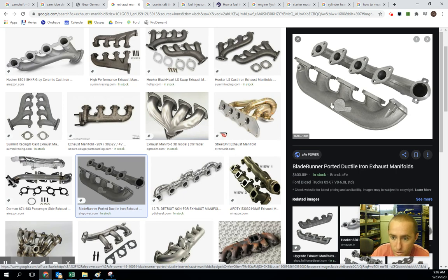So I have exhaust gases traveling this way and moving out towards the back of my car. That also creates a little bit of a vacuum in here, and it will pull the next exhaust and aid in this process so you don't have stagnant exhaust gas sitting in here. As this exhaust gas comes down here, it creates a low pressure zone in this area. And then as this comes through, it's going to help pull that exhaust through there as well.